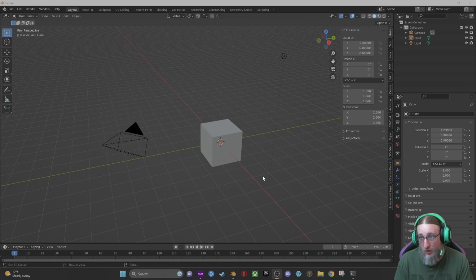Okay, next is going to be scaling it. So I'm going to come out of edit mode, and I'm going to hit 7 on my number pad. And if I look over here on my dimensions, it looks like it's 1.499 by 1.0. Okay, so it's 1.5 by 1, basically. So as we scale it, that means this is going to be 1.5, basically 1.5 millimeters by 1 millimeter. We want it to be obviously a little bigger than that.